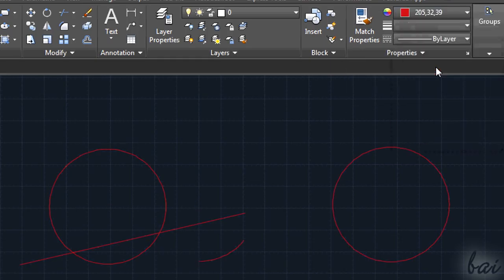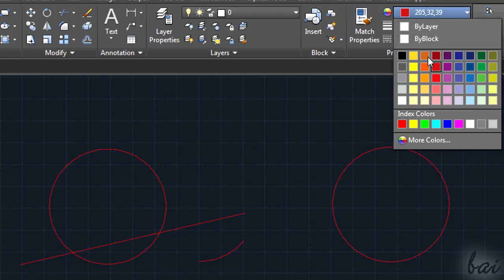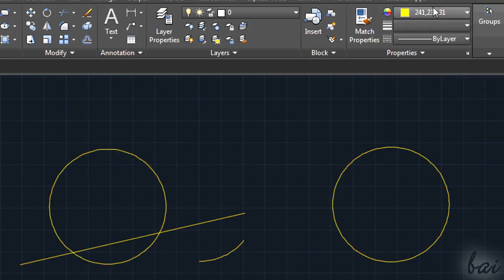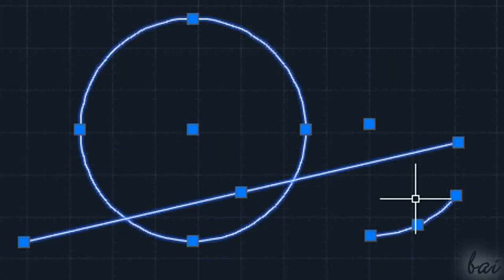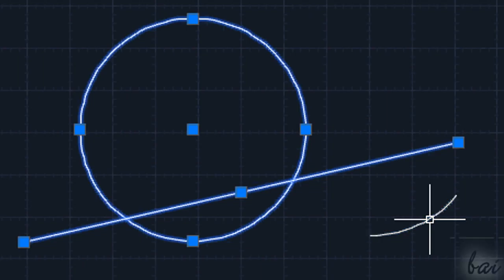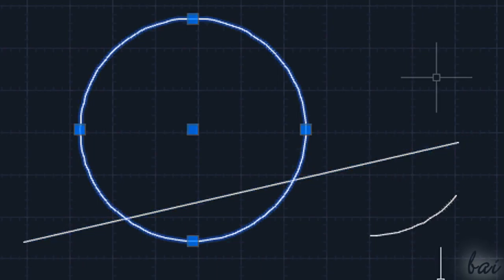If you have more objects selected, this will be applied on all of them. To select more objects, just click on them on and on. You can remove objects from your overall selection by clicking on them while holding Shift down. In this case, a small minus sign appears next to your pointer.